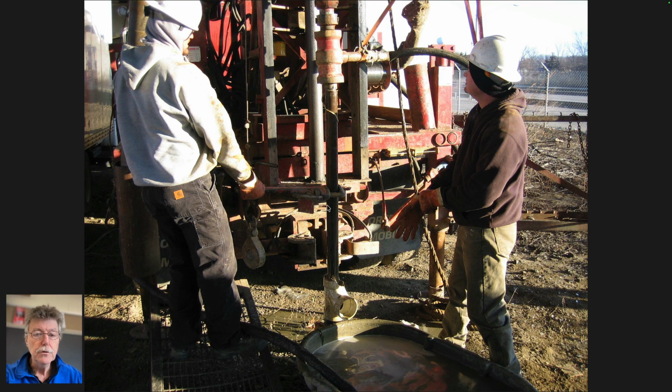So if you want to remove it, you'll take it up into the drill mast. You'll hold this portion so it doesn't move, and you'll wrench it. So you take it against the threads and unscrew it. So this would allow you to unscrew this piece. I guess it's grabbed here against this stage, so it won't fall down the hole. You take off this coupling, or you add this coupling, and then you raise it into the mast and be able to take it off piece by piece.